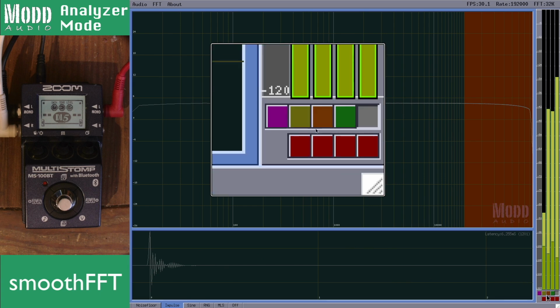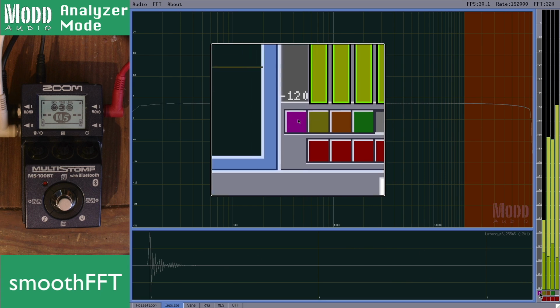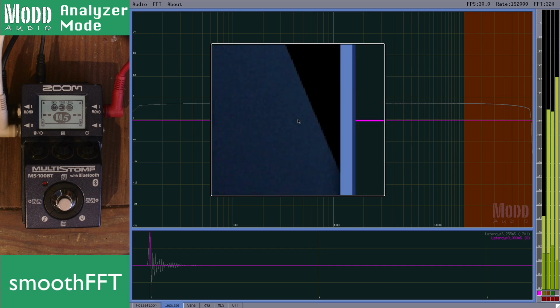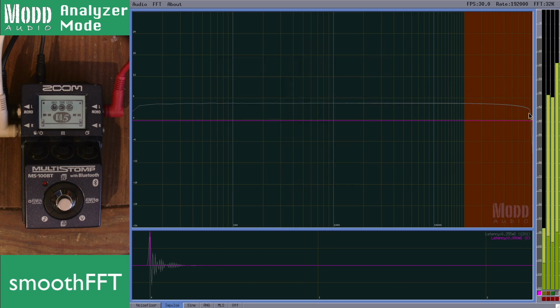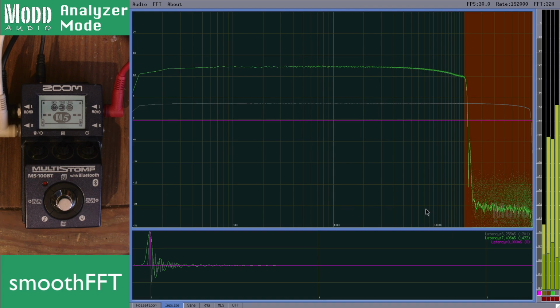But suffice to say, you send a single sample out, you get a squiggle back, which represents this curve right here. Basically, an audio interface can't generate anything above half its sampling rate, so it has to filter out anything above that. This can also show the frequency response of any device under test.